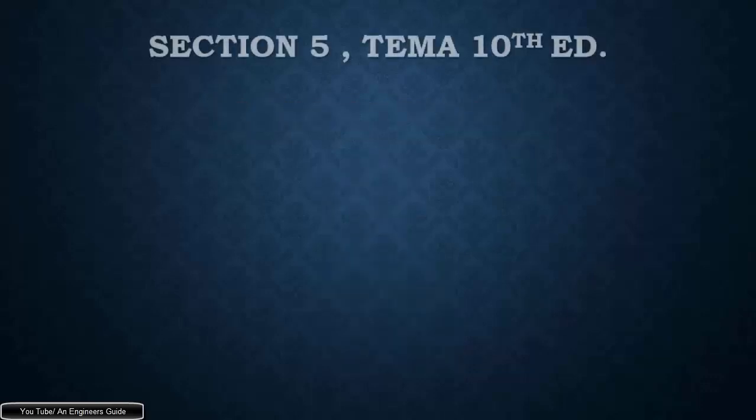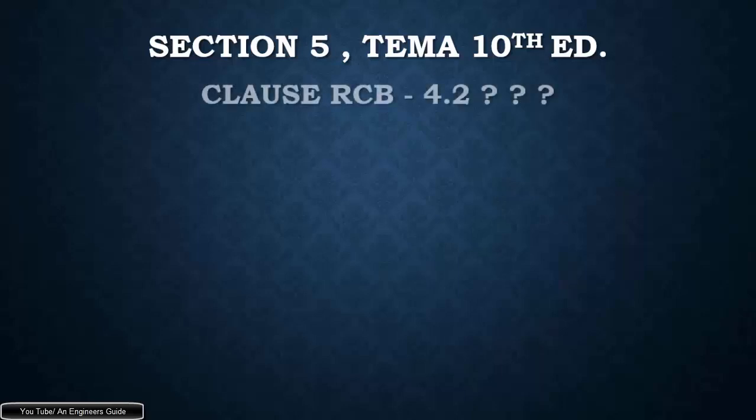So guys, to find out the solution, first of all, you should know the TEMA 10th edition. TEMA is the Tubular Exchanger Manufacturer Association. It is a standard used to design a heat exchanger. In that, just go to Section 5. In Section 5, find out the clause RCB 4.2.